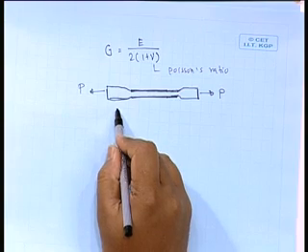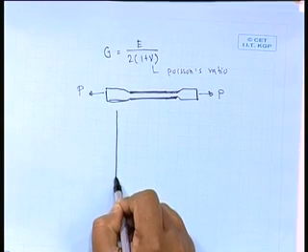There should be some instrument where the specimen can be put and we can apply some tensile force, and there we can measure force corresponding to the elongation of the member, or stress with the strain, and sometimes we can get a continuous plot of the load and elongation.